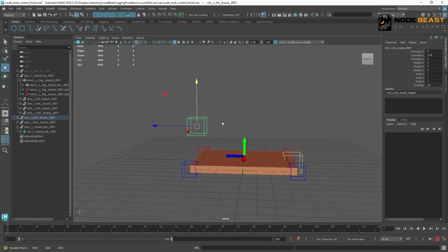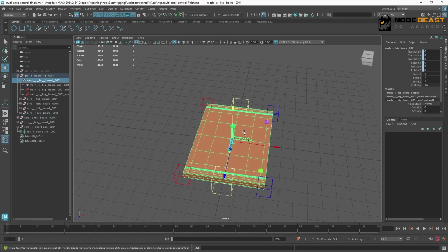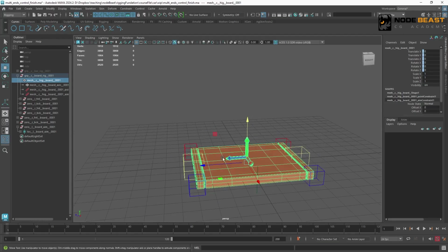If the rotation direction is front-back, how do we do the aim constraint? It's actually the same. We can just have the z-axis always point at the front object, or use the negative z-axis to point at the rear object. It's all the same, as long as it satisfies the effect of being on this line. But what's the problem here? The model already has an aim constraint. We're requiring its x-axis to point to the left side center. So how can we require its z-axis to point to the front center at the same time?